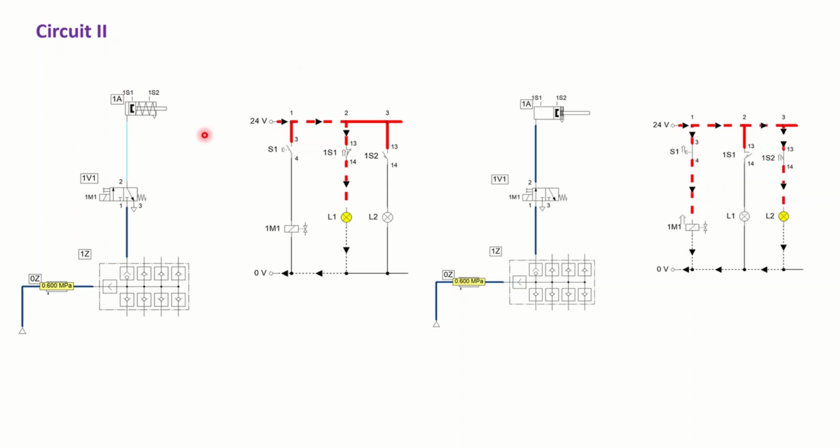And if we look at this specific circuit, once it is designed, we start the simulation. This make switch is linked to the fully retracted position of this single acting cylinder, so this lamp L1 is in on condition. That is sensing that position, and because of that sensing, this lamp is on. Because this is closed, current can pass, and we have lamp L1 in on condition.